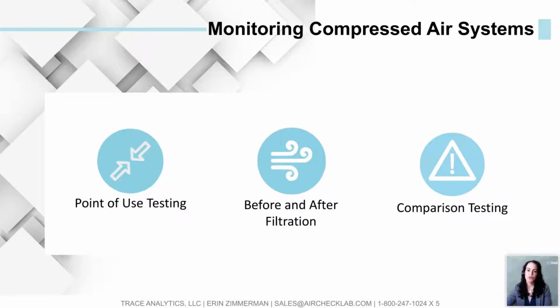And just like no two compressed air systems are alike, the same is true for your monitoring plans. They're not going to be the same for everyone. And that's because particles, water, oil, and microorganisms can already exist in your compressed gas, or become introduced, like I said, through intakes, leaks, or even improper maintenance. We always recommend doing a point of use test for both purity and contaminants on a quarterly testing schedule.